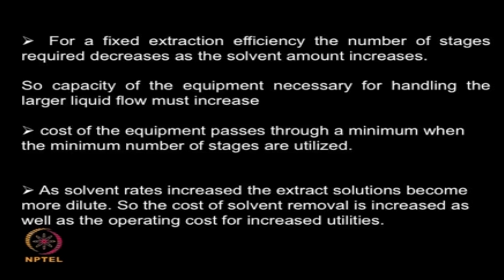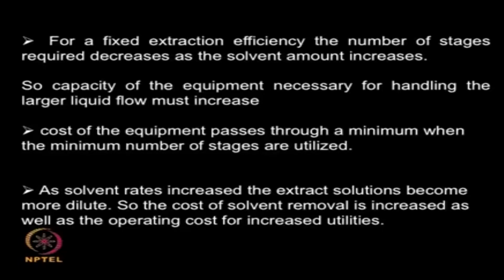Is it good to have fewer stages which are very large, or more stages which are very small? Because this type of contradictory forces are at work, the cost of the equipment passes through a minimum. That means you will have a minimum number of stages utilized.